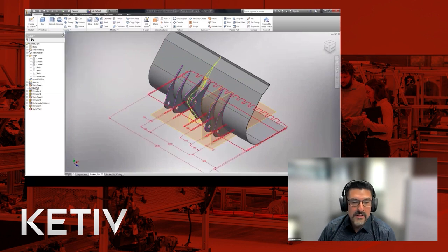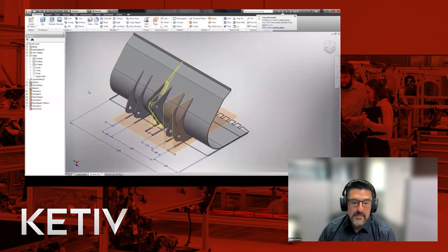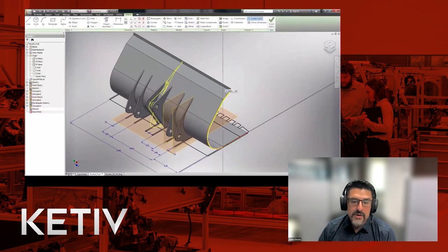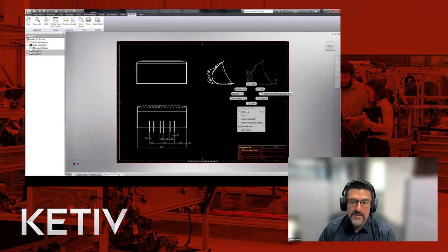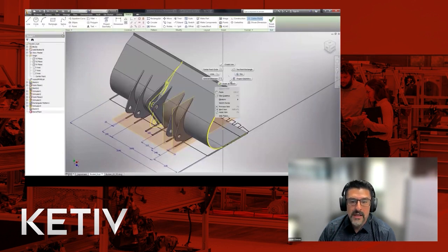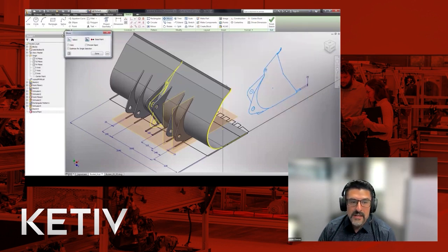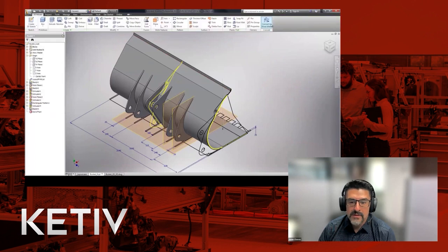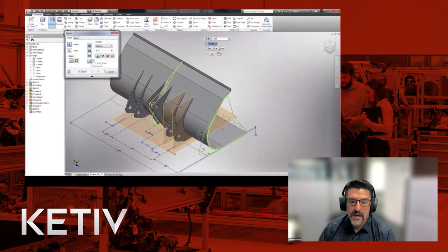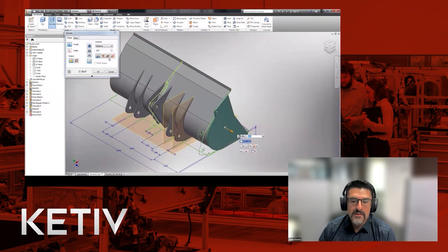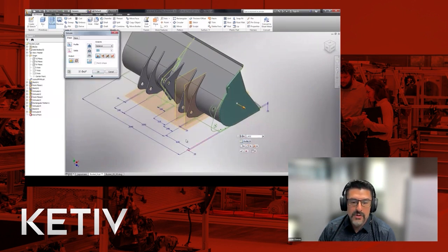There is a process or a way to bring this to an assembly level and explode it as you create different bodies. But for right now, we're just going to bring in one last sketch, and we're opening up AutoCAD again, pasting into another plane where we created a sketch plane. The details on how to do this, we've got tons of videos, and we're going to send you links for that. But again, we're extruding maybe another side plane here to create more plate geometry on the side, and of course the bucket teeth are going to get extruded there and reference a dimension from that side sketch. So in the end, what's left is creating more bodies to represent each and every individual component.